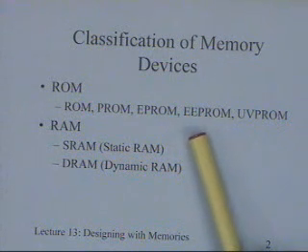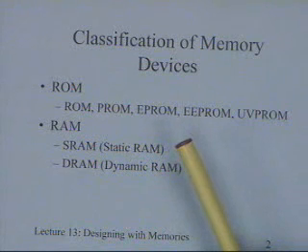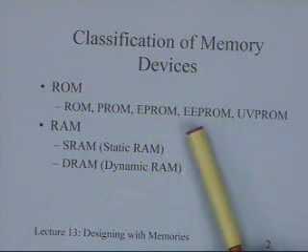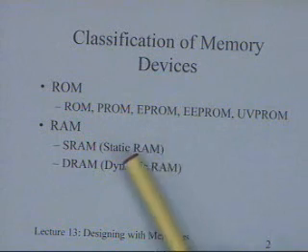The reading requires much less time, whereas the writing requires much longer time. It is not only that, sometimes the erasing is possible only if the complete ROM or a complete block of a ROM is erased. You cannot individually write into locations just like you can write in the case of the RAM.